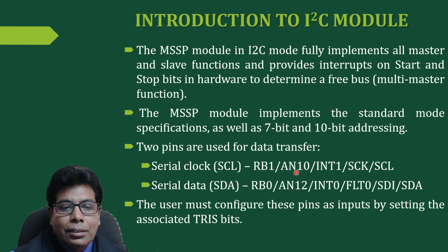So these are all the pins of PIC 18 family processors. They are multiplexed. That's why here we have shown RB1, AN10, INT1, SCK and SCL. Out of this, we are going to use the SCL part, that is the serial clock part. That will be the input.